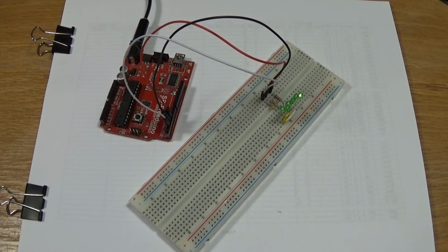In my previous video, I showed you how to blink a series of LEDs like these by controlling the individual bits in the I/O port registers to turn the I/O ports on and off and set them high and low to get the LEDs to light like this. And if I let the microcontroller run at full speed, you wouldn't see anything but a blur of LEDs. They'd all appear to be on.